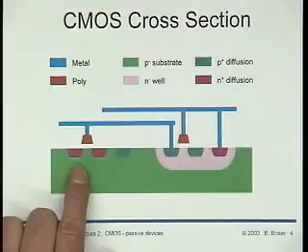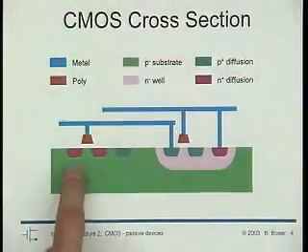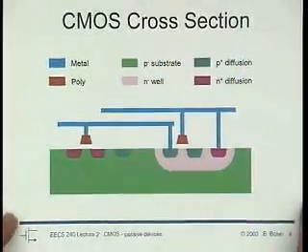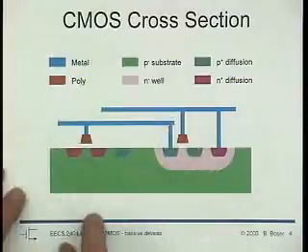But they're slowing things down, so a surefire way to come up with this next revolutionary A to D converter that goes at 1 gigahertz, and that is going to make you famous and give you a PhD, is to ignore all these junction parasitics, and it's going to go a lot faster, at least in SPICE. When you're fabbing, of course, it's a little different story, and so you may have to delay your PhD a little bit on that. So it's good to look at that.